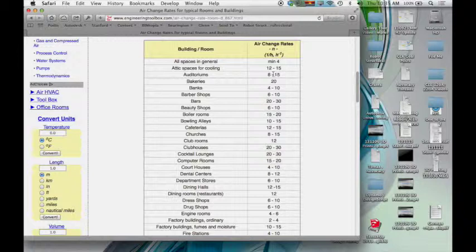Okay. So, mathematicians in the crowd, multiply that all together and come up with, clearly, you're not balancing my checkbook over here. Okay, 8,000 cubic feet more or less in this room. 4 air changes an hour means I have to move around 32,000 cubic feet per hour.